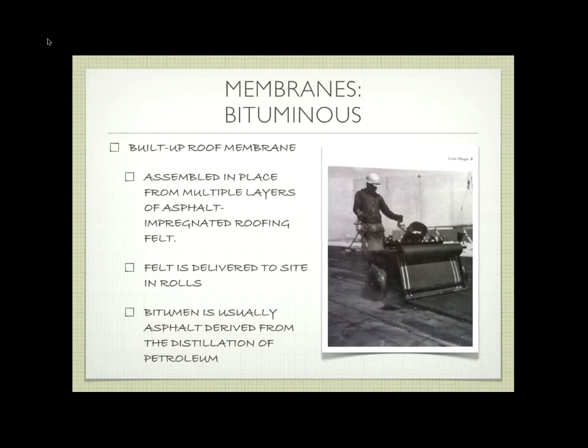So this is the felt. Yeah. Is that when they're sitting up there with a torch? Yes and no. It depends on the exact method. Okay, you can do something like this where you're applying the hot tar to the rolls themselves and laying them out. Sometimes it's going to be slightly different where the material itself has the asphalt layer on the sides, and you'll flame it to heat it up, and then when it laps, it'll actually seal.